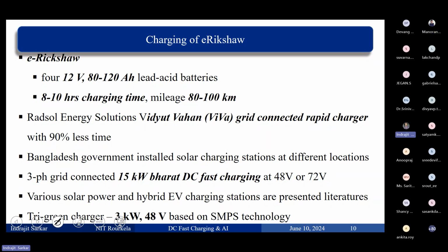They said they have chargers with different current tapping, and they always keep the current level going to the battery on the lower side. You can change the tapping manually, you can change the current level going to the battery, but they are saying that they don't do that because it heats up the battery.